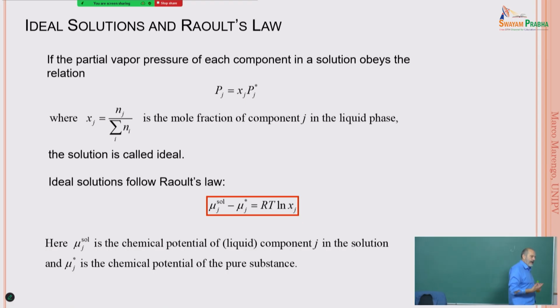How can you check how much gas is inside? Well, you need to consider that when you have a second component inside, the saturation pressure doesn't correspond anymore to the saturation temperature for the pure fluid. So if you are considering a given temperature, you should expect a given pressure. But if you have dissolved gas inside, you're going to find a different, lower pressure.